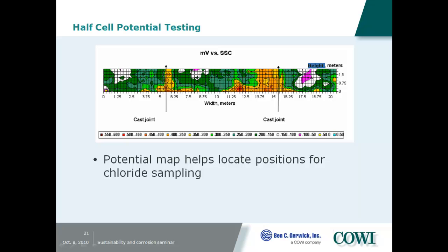You then check where you are on certain areas. You have to confirm that you have corrosion where you expect it, but you also have to limit the extent of corrosion by testing also where you have a value which is an uncertain corrosion. It's a very strong tool. We normally combine it with sampling for chloride, so you can combine results from different testings in your evaluation.